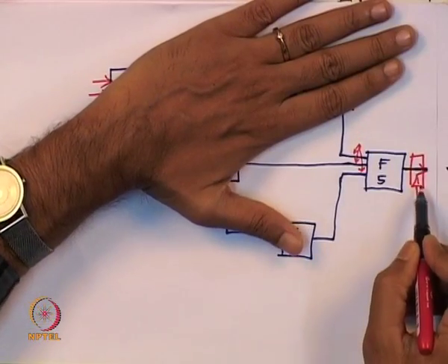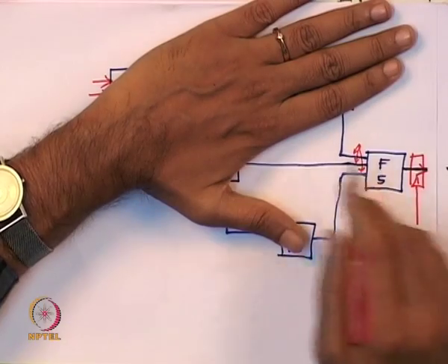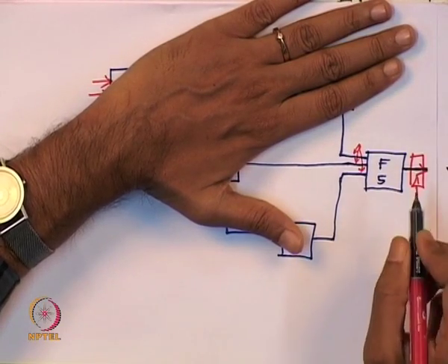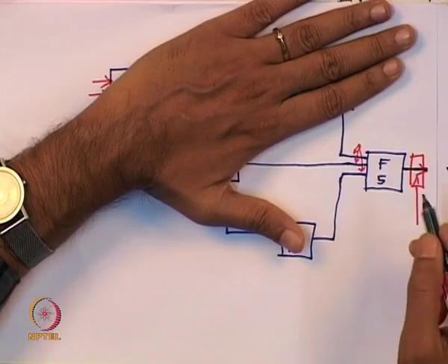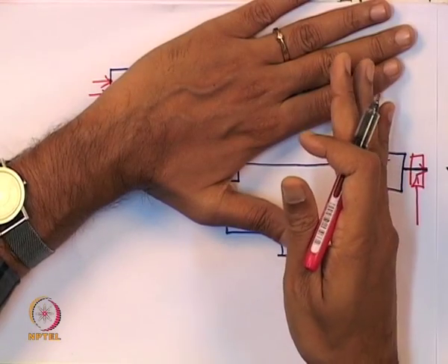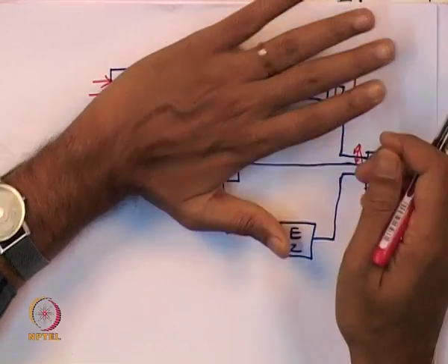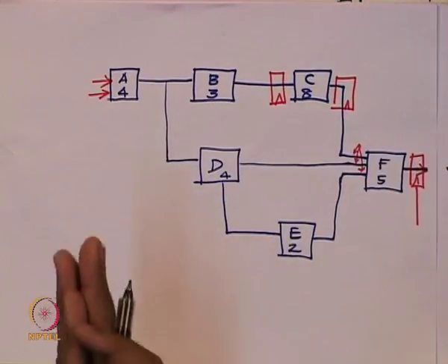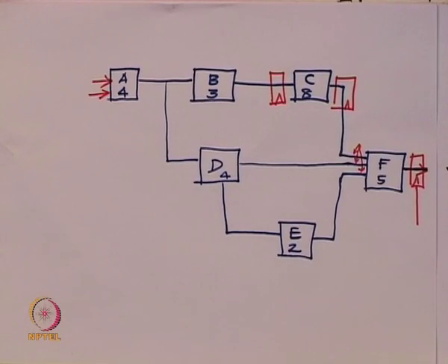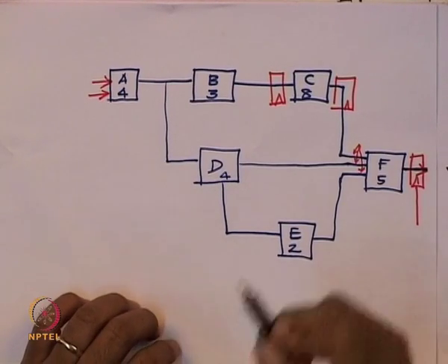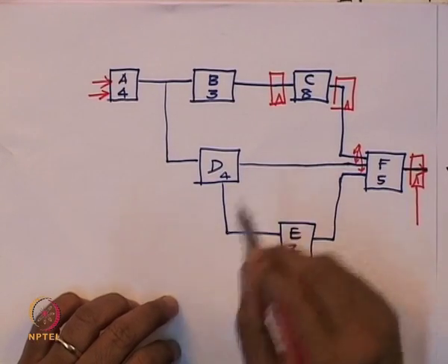If I put only this one flip flop, it will be a one stage pipeline, which is not quite useful. It will still have a latency of 20 nanoseconds, so it is not making anything better. When looking at pipeline circuits, you are asking for either a 2 stage pipeline or more.